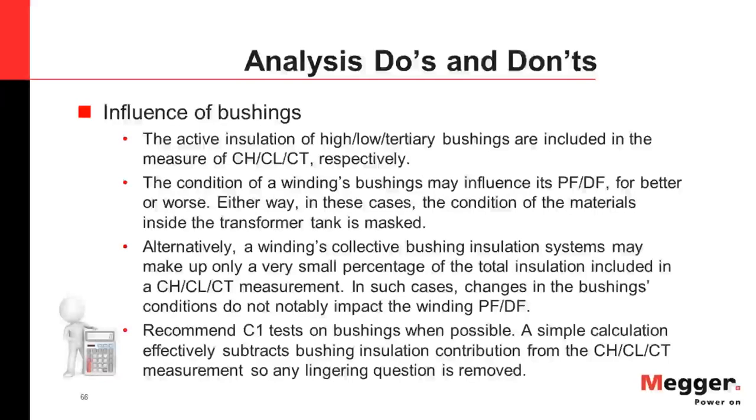and then a simple calculation, which is nowadays automatic in most software. This simple calculation will effectively subtract the bushing insulation contribution from, for example, the CH measurement. So any lingering question about whether your CH measurement in this case is off because of something the bushings contributed, that question can be eliminated fairly quickly. And do keep in mind that trending is the number one way to analyze power factor or dissipation factor.